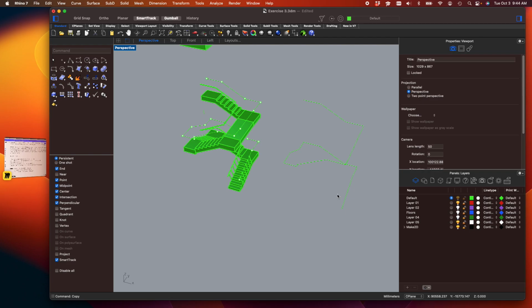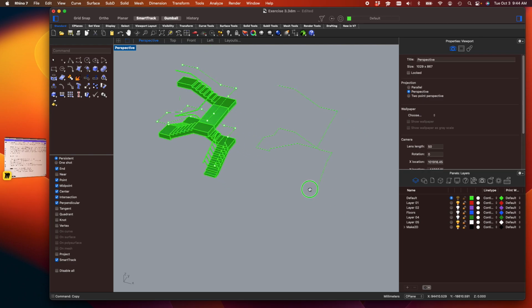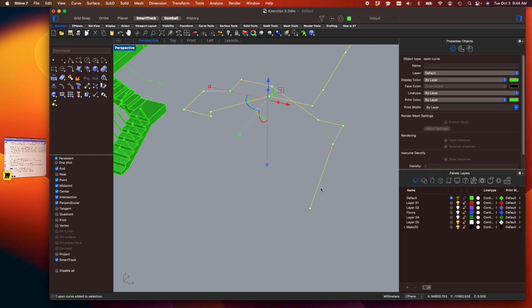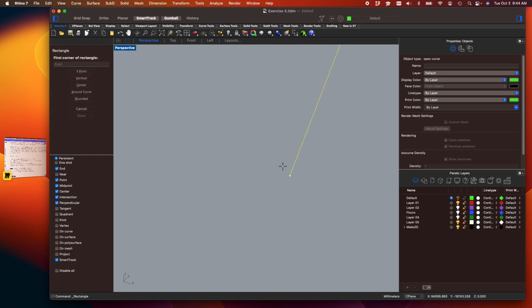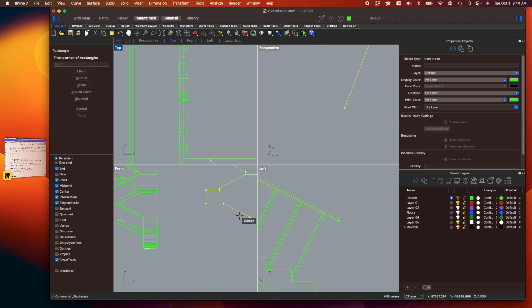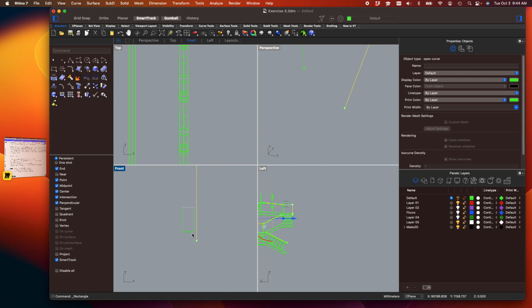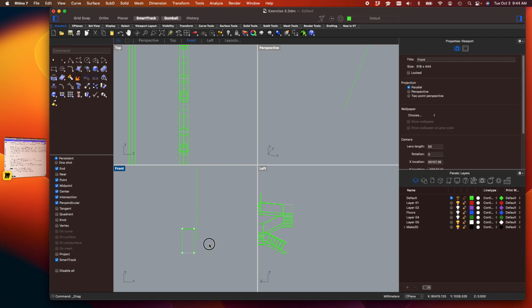However, a really cool modern stair is one stringer in the middle and they're sort of placed on it. I'm sure you've seen it before, but what it ends up being is a little bit more structured. So in my case, I'm going to start with maybe a 6 by 12. Right, so I'll go with 6 inches by 12, and I'm basically just going to sweep that. So I'm going to get as close to the middle as possible of that profile.